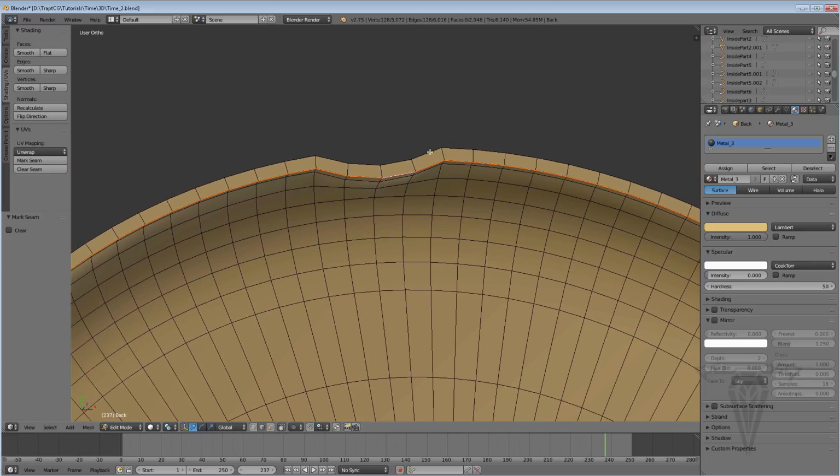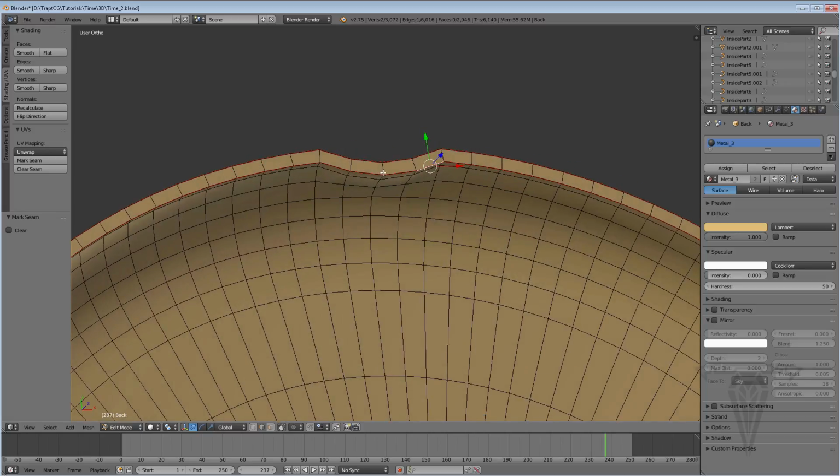Let's get this other edge on this lip here. So I'm going to hold down Alt and click to do another loop. Now I could, again, click mark seam here or in any of the other locations, or I can hit Shift R. Now Shift R is repeat last action. So the action was creating a loop seam, and look, it created the loop seam.